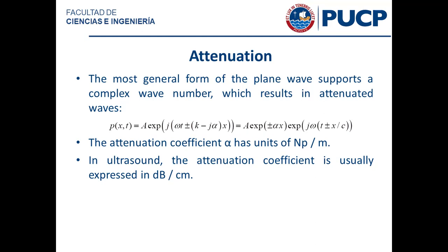What the damper did was reduce the amplitude of the oscillation because it opposed the velocity, just like the spring opposes the displacement, here via Hooke's law. The damper opposes the velocity. The faster you move, the stronger the force that opposes it, right? So it basically dissipates the energy over time.